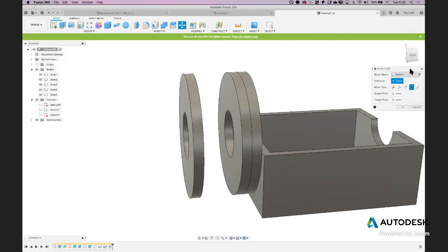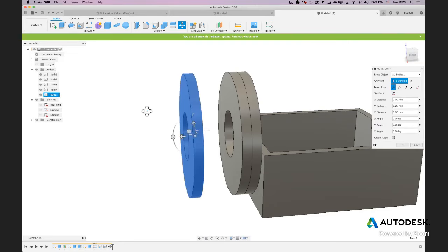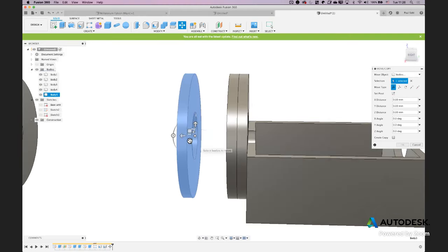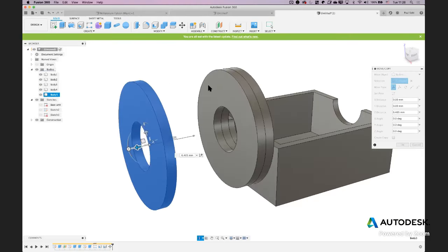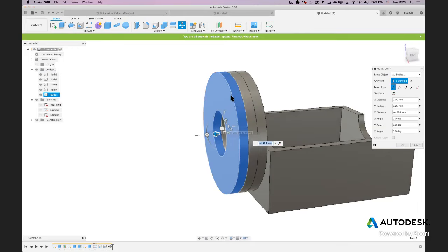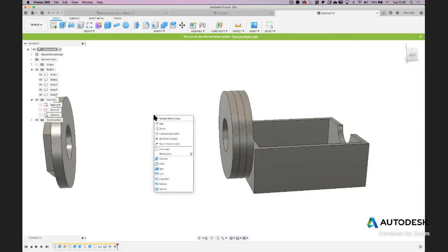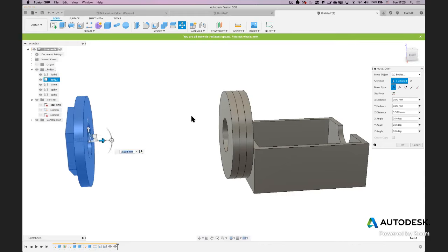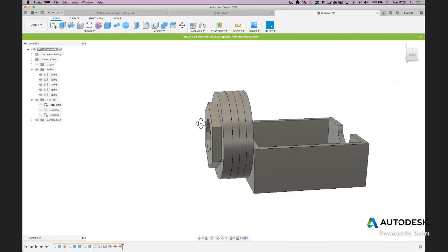Another way to do that, just to show you with the move function, if I'm just using the regular move and I tell it this is what I'm moving, now it's highlighted the origin point is at the same place where the other one was. If I grab that arrow and move it around and then just click on this surface, it's going to snap to it because it knows that I've already told it I'm moving in this axis and I want to move this where my origin of my move operation is coincident with whatever surface I've clicked on. So move that in place, and then let's just repeat that one more time. And I can do the same thing I just did there, grab that, and then just click once, snap, all those pieces are in place.